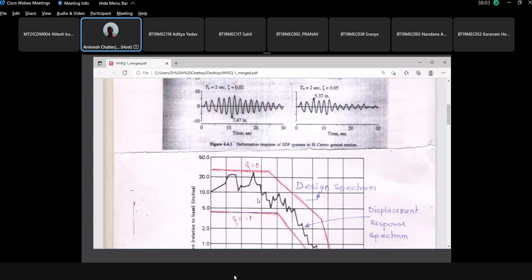Sir, it will go into resonance. Most of the students I know will say resonance will happen, but that is wrong. Why will resonance not cause failure? I mean, resonance will happen, but the building may not fail. Why? Say damping is 0. Sir, that maximum displacement happens for such a small time that it doesn't get time. That is the main thing.